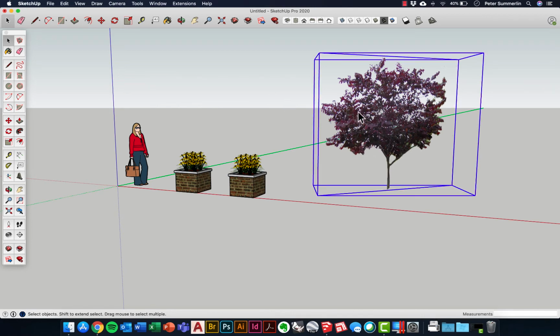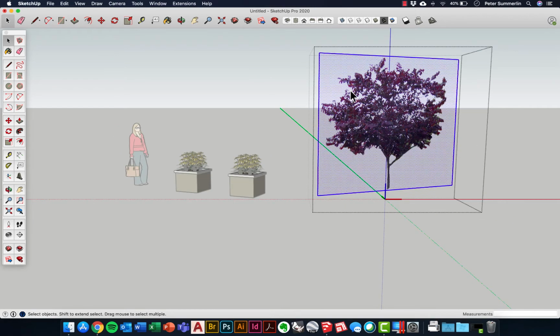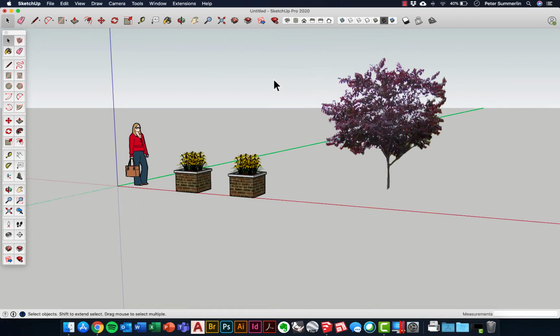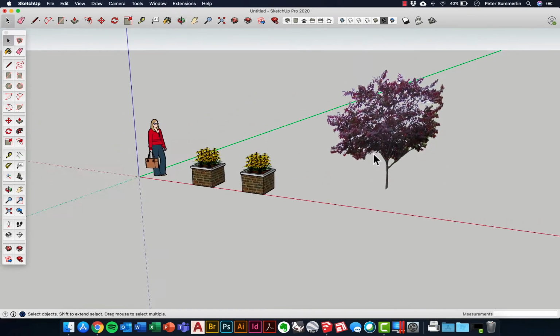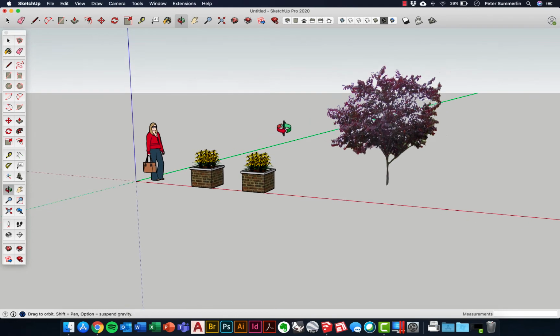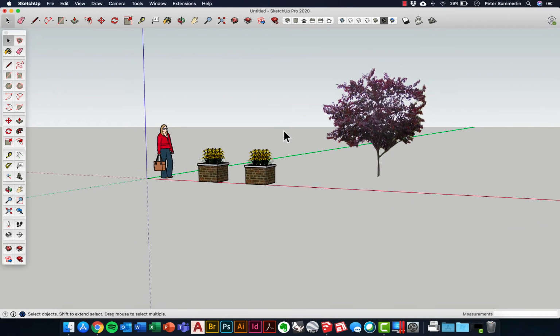and if you were to export that with that box, that's just a dead giveaway that that is an image. So what I might do in here is double click on this right here. Once we're inside, it selects both the image and the outlines. I'm going to hold Shift to deselect that image. Now I can right click on the lines and just hide those right there. They'll disappear so I don't have those lines. Another thing to do is to go into your styles and adjust the edges for those styles, and you can make it go away that way as well.